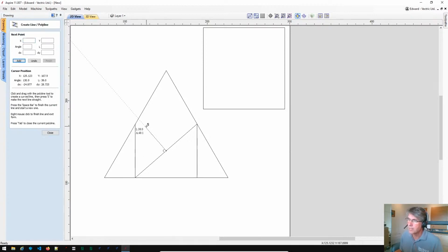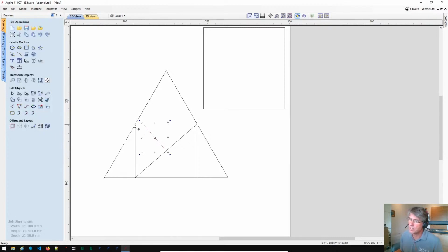Okay, so as I've come out, I'm just drawing a line that is 90 degrees off here, but obviously it's not going to connect up with that. So what I do instead is I can just drop that back on to the end point there. So now what I've got is this line, and if we were to continue it out, it will intersect that line at 90 degrees. Slightly awkward way of doing it, but that's the best we can do at the moment with our smart snapping. I'm going to take another copy of that, so I've just dragged it. I'm going to hold down the control key as I snap that endpoint onto the other side, so that we now have these two lines.